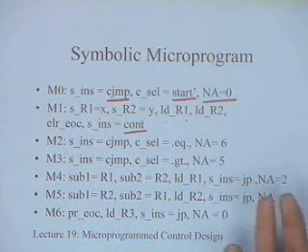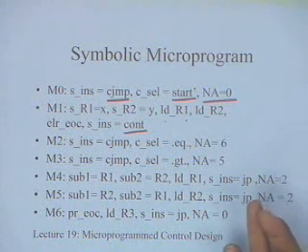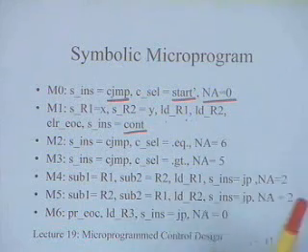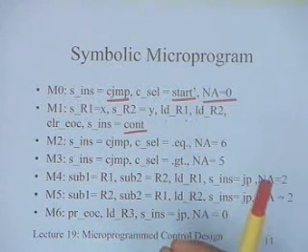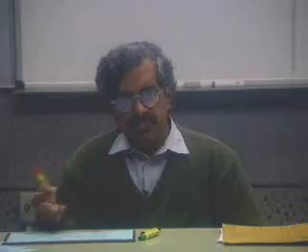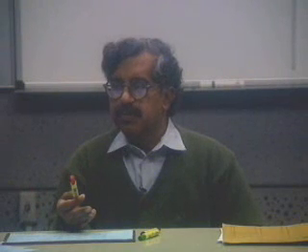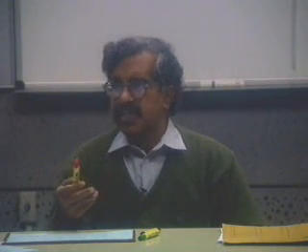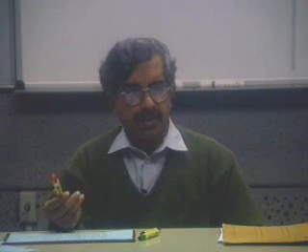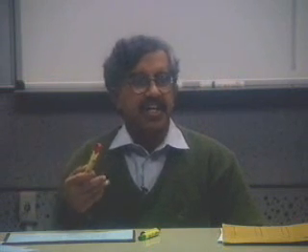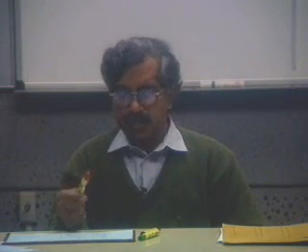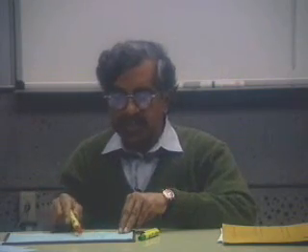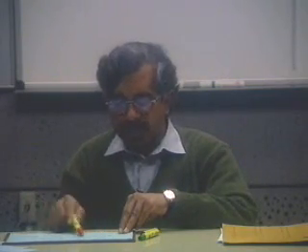Both of them are 16 bits wide. All our operations are 16 bits, so please remember that for both this comparator and subtractor, if it is a ripple carry type of circuit, the delay will be proportional to the number of bits. So there will be substantial gate delay in both the subtractor and the comparator. So I have to leave one clock cycle for this comparison operation.